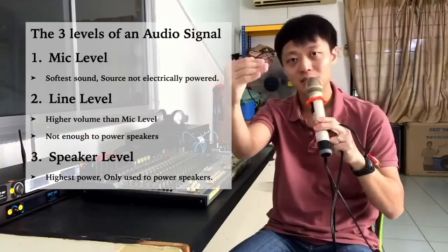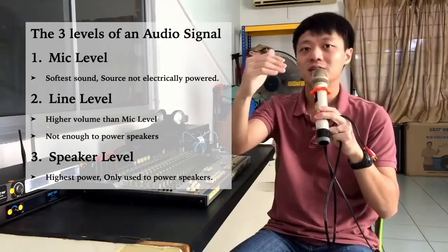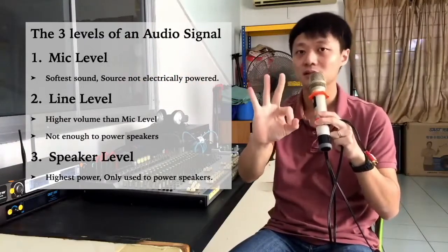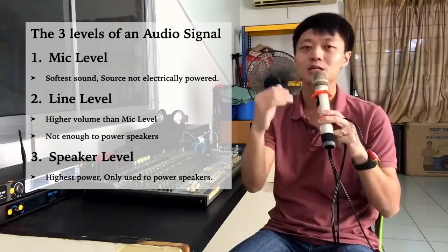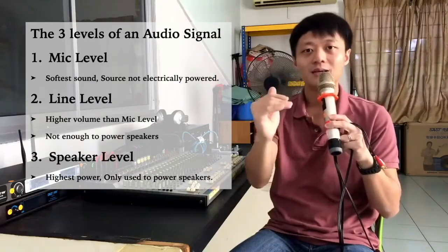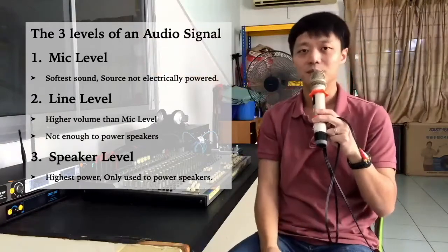Then the third level of audio signal we call the speaker level. The speaker level carries a signal at a very high voltage, enough to power up the speakers in our church. That's why it's called the speaker level. So there are 3 levels of signal that I want you to know today. The first is mic level, the softest. Then the line level, which is at a medium level. It's not so soft but it's not so loud. And then the third level, the speaker level, which is the loudest of them all, and it allows you to power up the speakers up here.